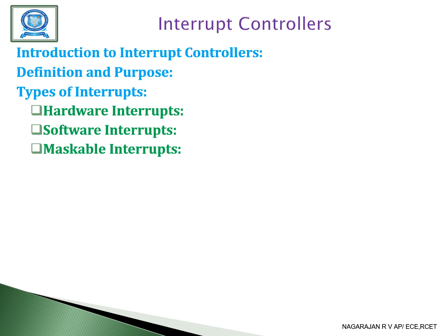Maskable interrupts are commonly used in scenarios where the system needs to complete a critical task without being interrupted. The next one is a non-maskable interrupt, NMI. It is a high priority interrupt that cannot be disabled by software. NMIs are used for emergency tasks such as responding to hardware failures, system errors or critical power management events.